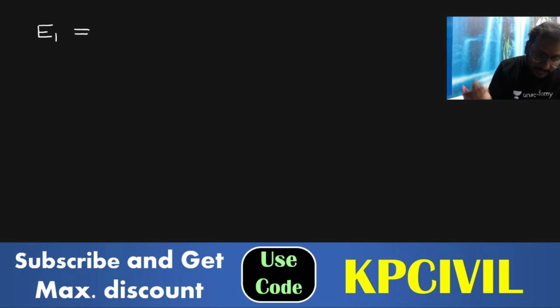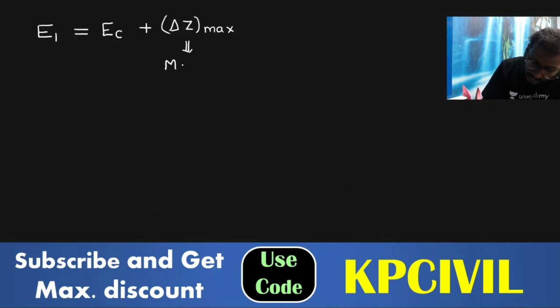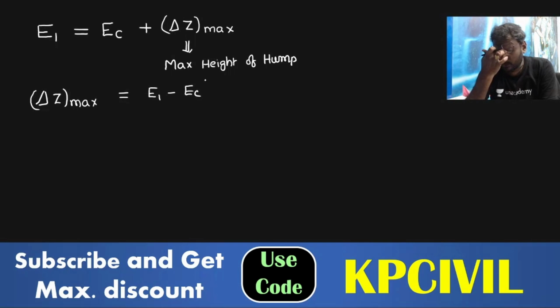Energy at point P, E1, is equal to critical energy plus height of hump. That delta Z max we are now considering as the maximum height of hump. Whatever delta Z max you are getting here is considered as the maximum height of hump. So delta Z max is equal to E1 minus EC. You have to derive critical energy and energy at P, both. E1 is energy at P, EC is critical energy.